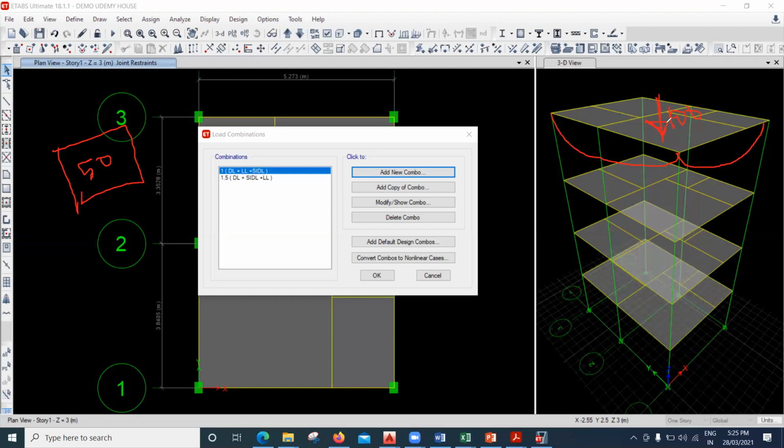So here we are not going to put factor of safety of 1.5, because this 1.5 what we are putting, like I mentioned, 50 kg is a load, but I'll design it for 75 kg. But I don't know in future whether this 75 kg will come or not, but I'm taking from future point of view. But for limit state of serviceability, this 100 kg is exact. Instead of this 100, I'll speak for 50 kg only. I took example as 50 kg.